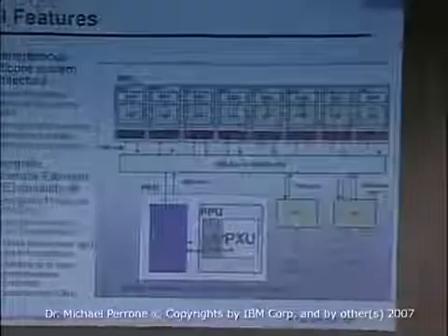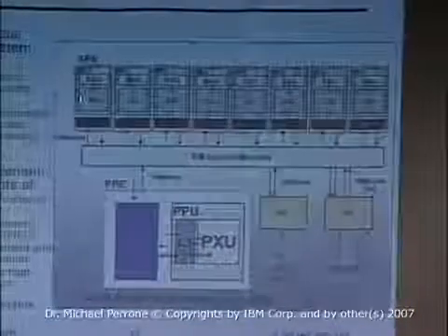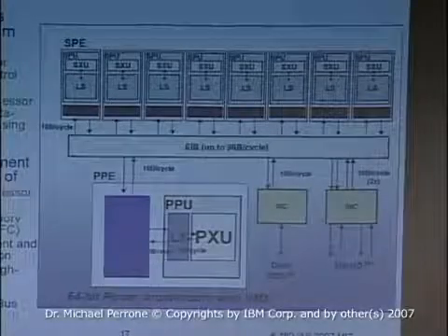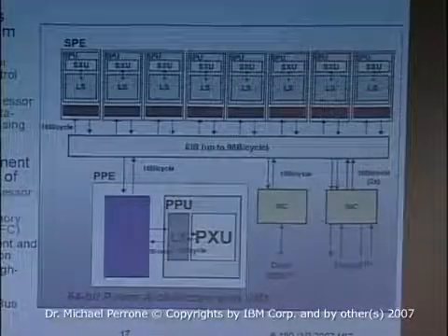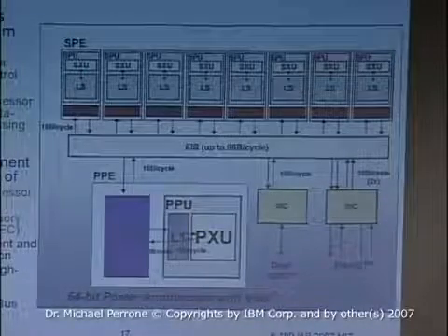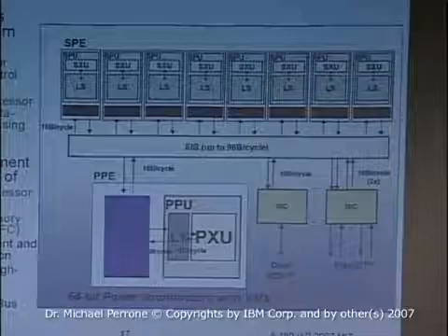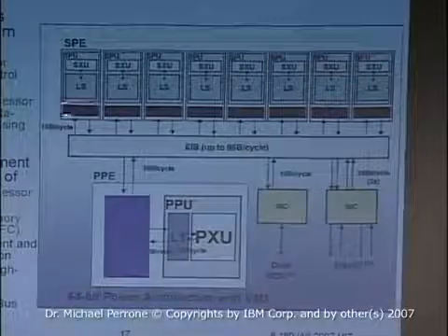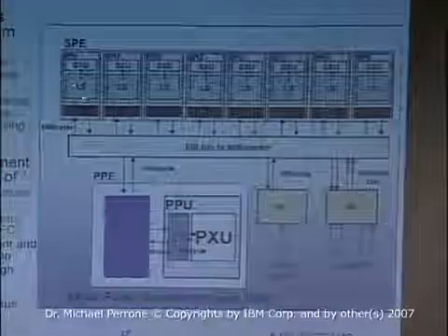It's not very large. It's a quarter of a megabyte, but it's very fast to this SXU, this processing unit. It's only 6 cycles away from that unit. And it's a fully pipelined 6 so that if you feed that pipeline, you can get data every cycle. And here, the thing that you can't read because it's probably too dark is a DMA engine.